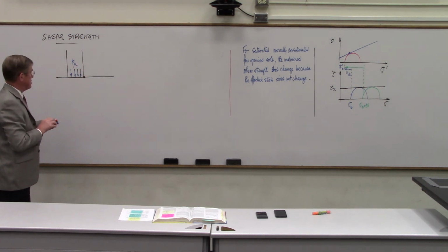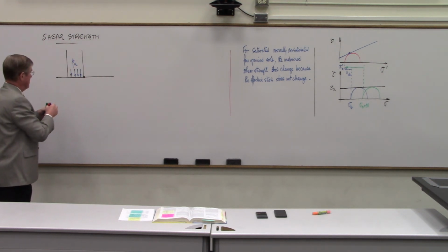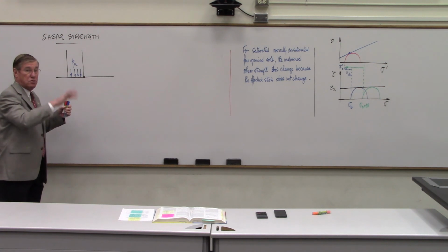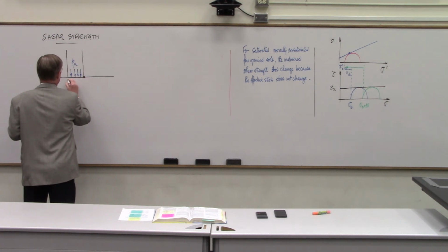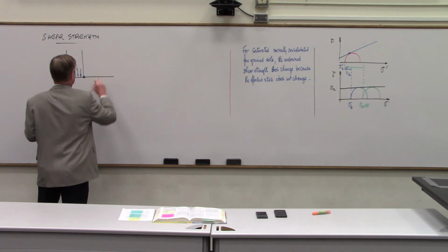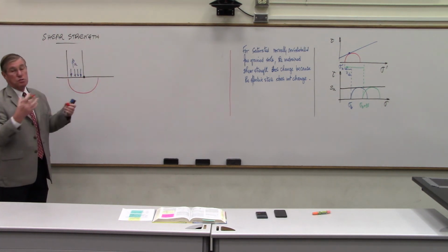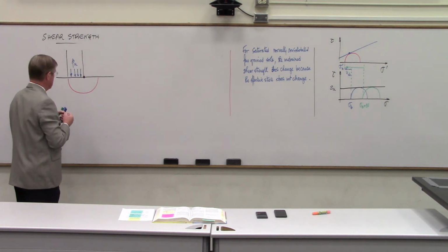And then we're going to say, well, if this tower is going to collapse, it's probably going to rotate and make the soil rotate along a certain failure pattern. And we're going to say, well, what about a circle? So we're assuming a failure surface.